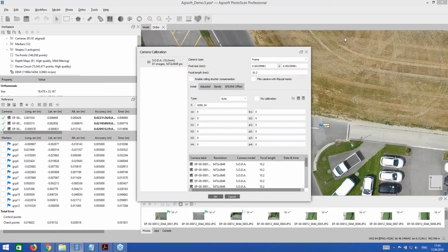But for the compact cameras, small digital cameras, we believe that the calibration is not necessary, and you can just let PhotoScan adjust the calibration parameters during the alignment stage and during the optimization stage. Usually that's because digital cameras may have some moving elements, and in some cases, shake related to takeoff and landing may affect the positions of the lens system.